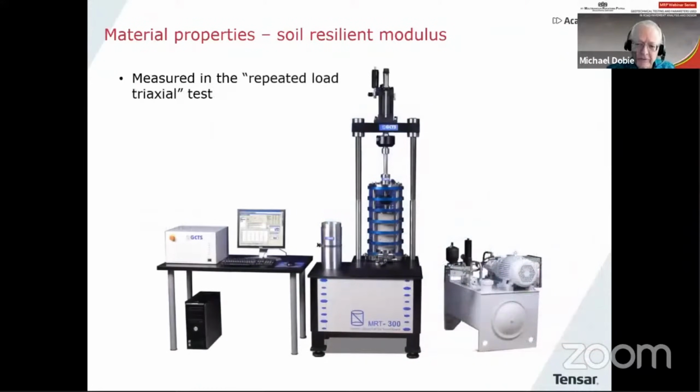There is the setup for a larger size aggregate, so it's a bigger piece of equipment. And we call this the repeated load triaxial test. You might call it cyclic load, but it's not quite right. It is a repeated load triaxial test. We'll see this in a minute.